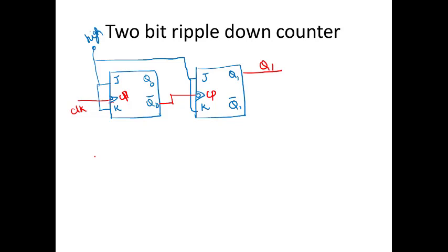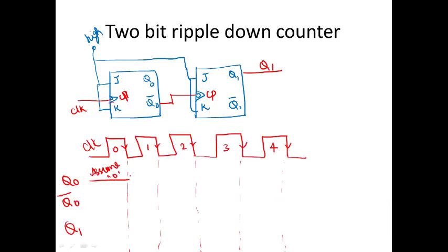And the timing diagram I will draw now. So again your output will be, assume that 0 for negative edge trigger clock, always your JK is tied to high. From here, whatever may be my previous output, you assume that you have my previous output here as 0. So now since your JK is tied to 1, I will be having a toggling from 0 to 1, because your JK is continuously tied high.